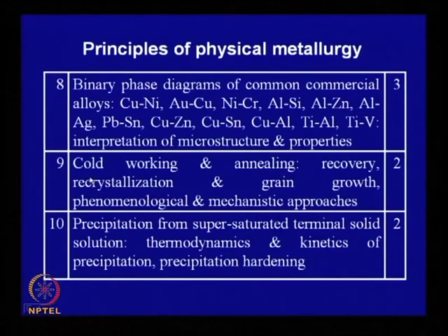Now, metals can be subjected to cold working. What is actually cold working, what are the properties that change with cold working, and how can you restore the properties and control the subsequent processes. It will be primarily a phenomenological and mechanistic approach. We will also know about the process of precipitation hardening, what happens when a supersaturated solution is given some thermal treatment. We will know about the thermodynamics and kinetics of precipitation.